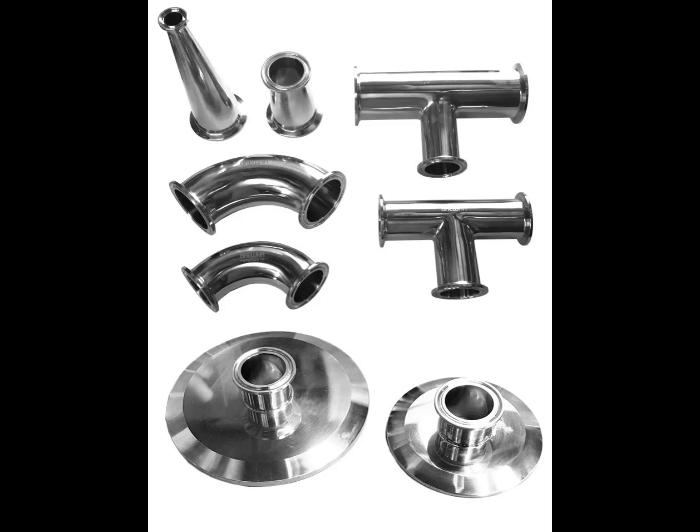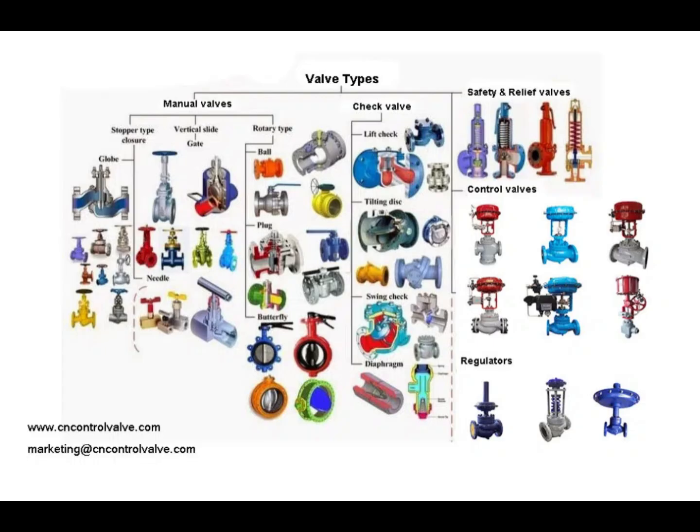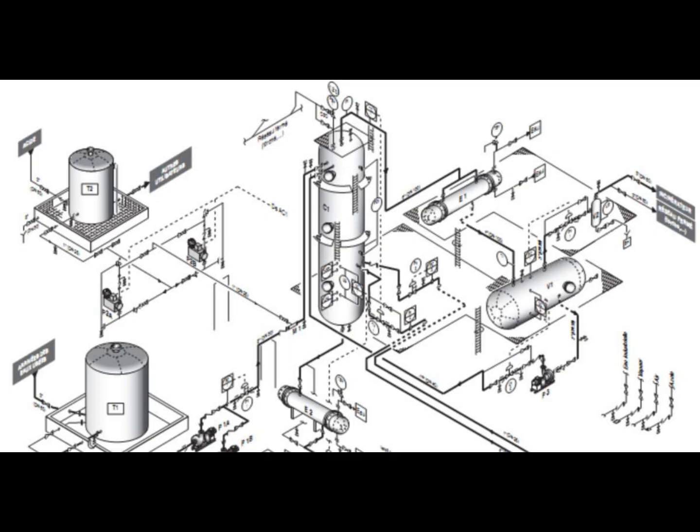Step 6. Include fittings, valves, and special items. Straight pipe alone does not represent the full scope. Always count elbows, T's, reducers, flanges, gaskets, and bolts separately. Valves must be counted by type, size, and pressure class. Pipe supports should be counted by support type and location, not estimated blindly.